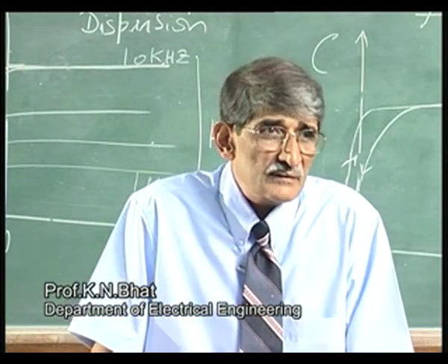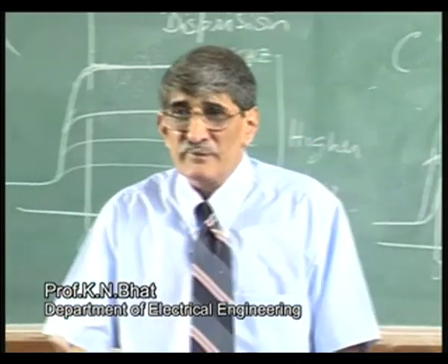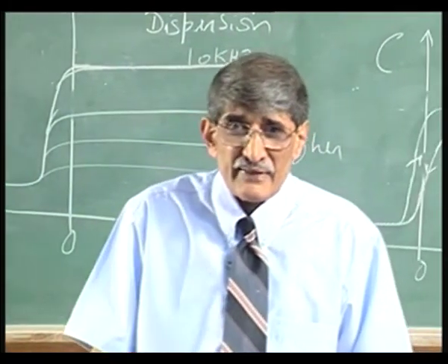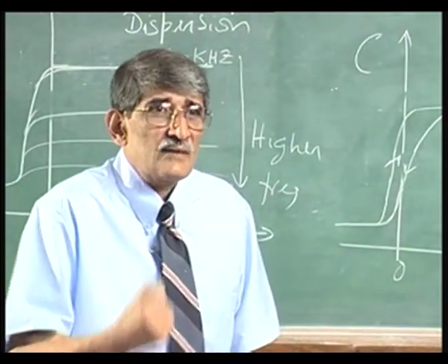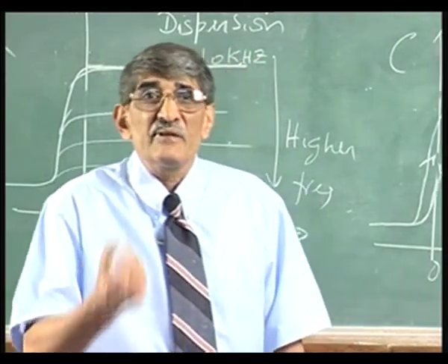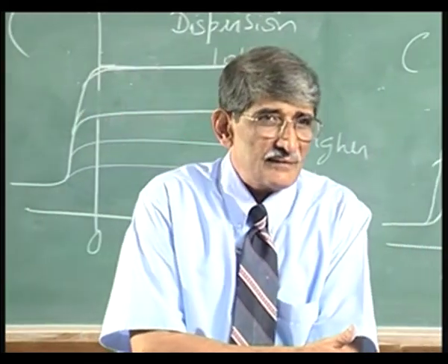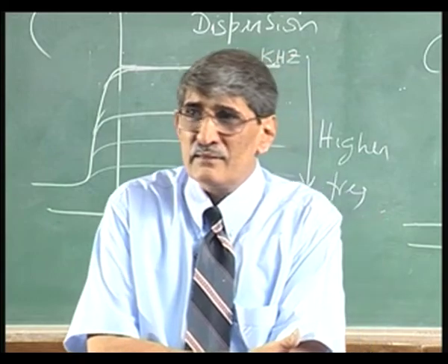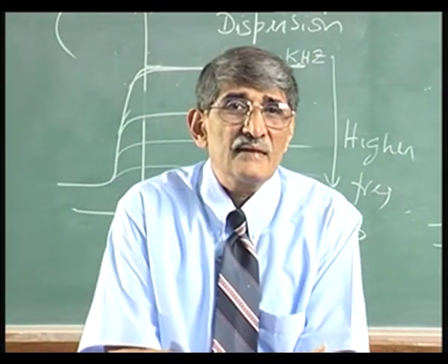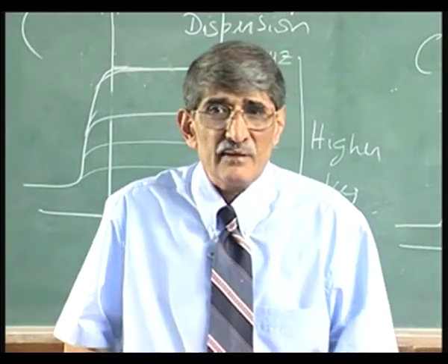MESFET does not work out in indium phosphide devices. That has got to be a JFET, or the last straw is the MISFET, the MIS field effect transistor. In fact, there is some drive to get MIS field effect transistors in gallium arsenide also.